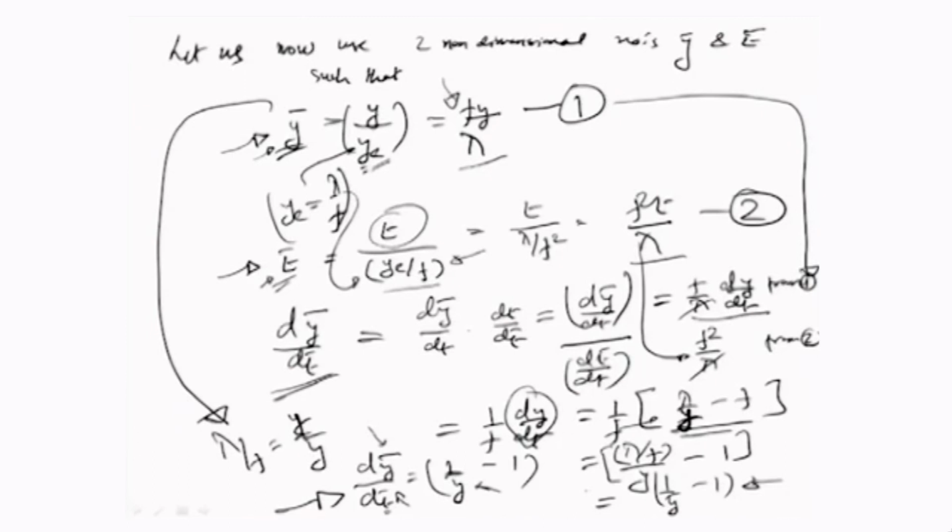Now what you can very easily observe is that this equation has gone independent of the feed, because the feed is buried inside the information for the time ratio t dash, which is equal to the equilibrium gap per unit feed, ye by f. That is how you have a relationship between all ratios, a non-dimensional relationship.